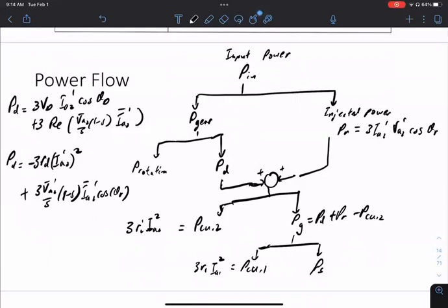So how does changing wind speed impact the power generated? Changing wind speed shows up as a changing S. So it will change the developed power. Changing your developed power will change your power to the stator. But I want to keep this constant. So now I need to change VA2 prime and theta R. But changing VA2 prime and theta R changes PR. But then I want the sum to be constant.